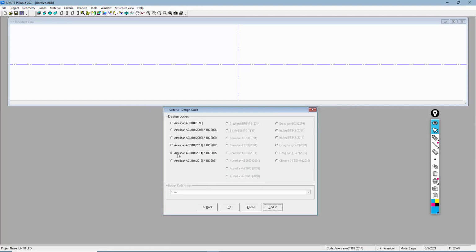Keep in mind that when we're using this program, the program is really always working in a new design mode. Even if we enter base reinforcement and post-tensioning that we know is in an existing slab, the program will actually tell us what additional reinforcement we need. But we also have the ability to produce as-built or existing moment capacities against the demands. And that's something that's important when we're doing an investigation.